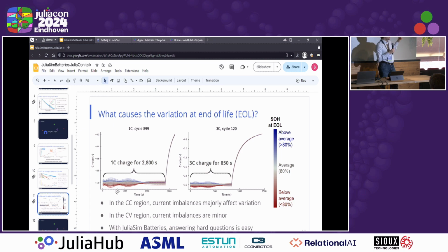And because they have been charged more, they have degraded faster, so this has impacted them more. And the ones in blue are the ones that haven't been charged so fast, and thus they have a longer lifespan left. We can see that if we compare 1C with 3C, the length of this interval here and here is significantly different. And this essentially is what would account for the difference in the distribution that we see for the cell-to-cell variation.